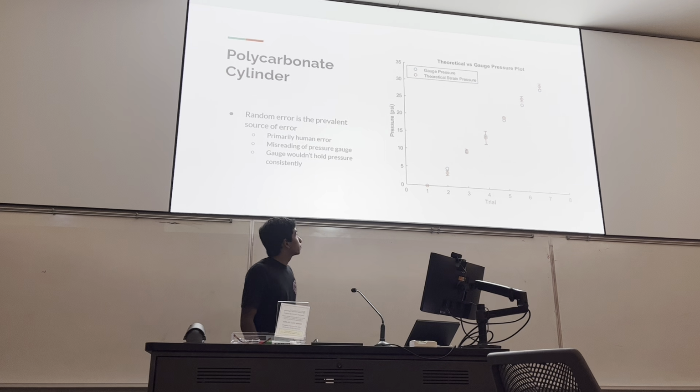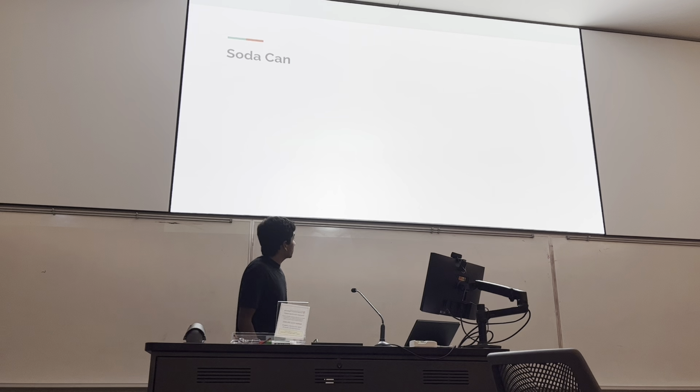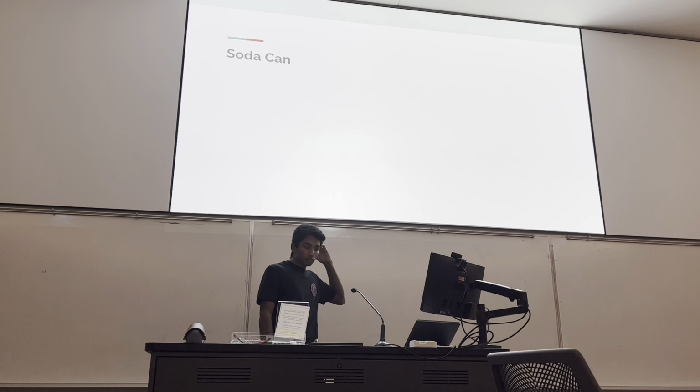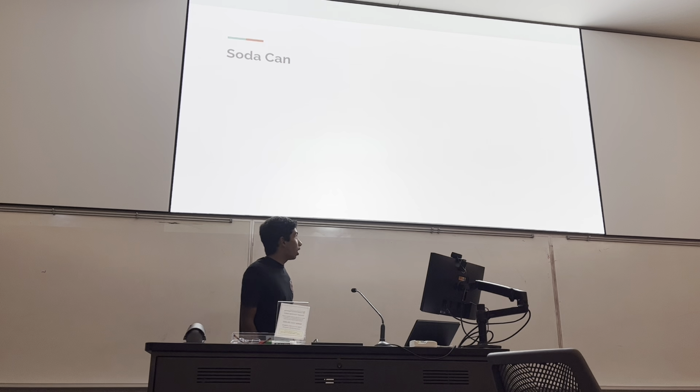They are pretty similar. So the second part of the experiment involved taking strain gauge measurements from a soda can that we opened. Again, the first thing we did wasn't just find the strain. We had to find raw and balanced voltage. They are given here and here.